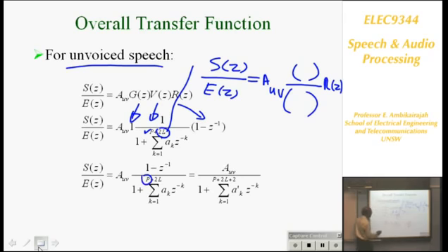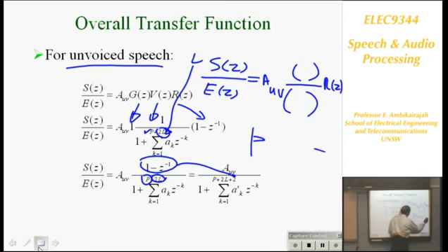Already there are P poles available, and if you've got zeros, you translate them into 2L poles. And you've got another zero here. You can put that also into another 2 poles. So eventually, for voiced speech, you need P poles. For unvoiced speech, you need P plus 2L plus another 2. That many poles you want. So now you may ask me, why am I doing that? Because I want to have a single transfer function without a zero. Then I can manipulate things later.